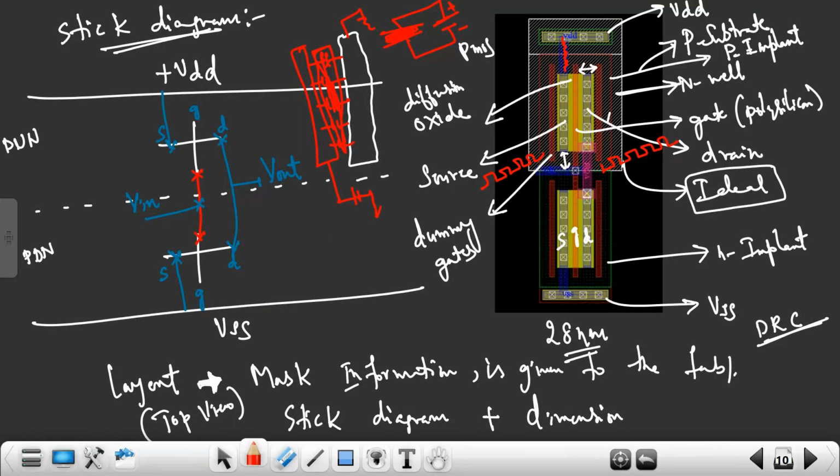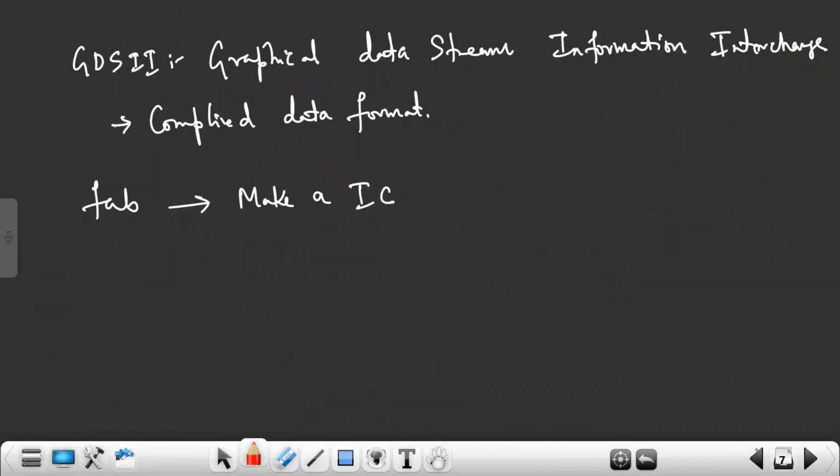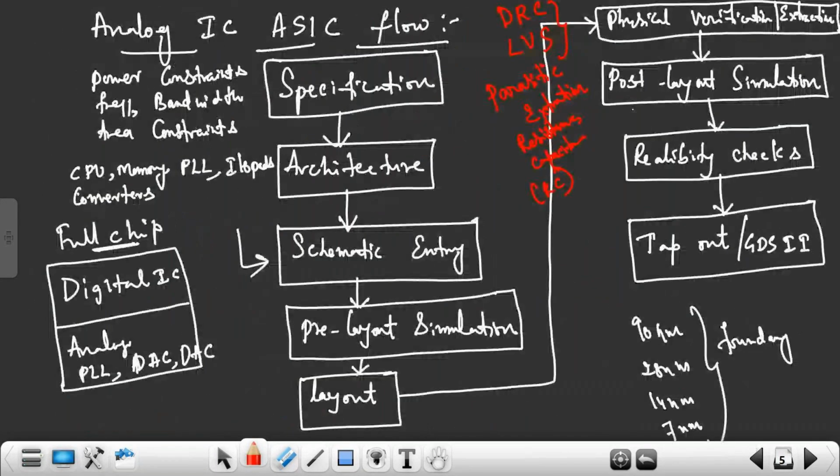But this output will vary because of the parasitic capacitance that is formed. We should reduce the parasitic resistance and capacitance to match the output of the pre-layout simulation to the post-layout simulation. Whatever simulation result you get from the first simulation, this result should match this one. And you should understand how this parasitic resistance and capacitance is impacting it.